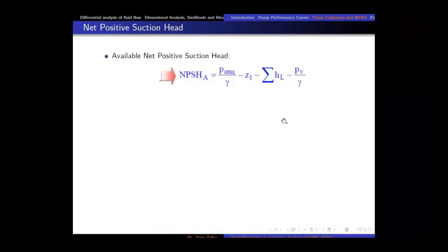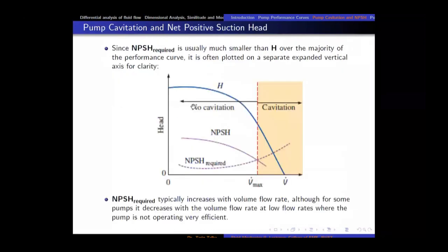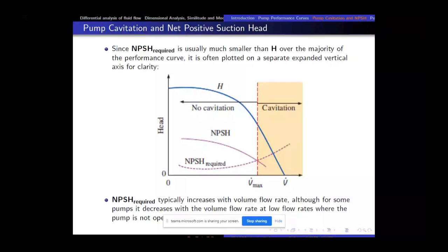Okay. So now, without doing any calculation, because in this figure NPSH available is on the higher side, we want it to be as high as possible. The required NPSH depends on a particular pump, and that is something we cannot change, right? Because that depends on the manufacturer. So we need to have this line as high as possible for the available net positive suction head, right?